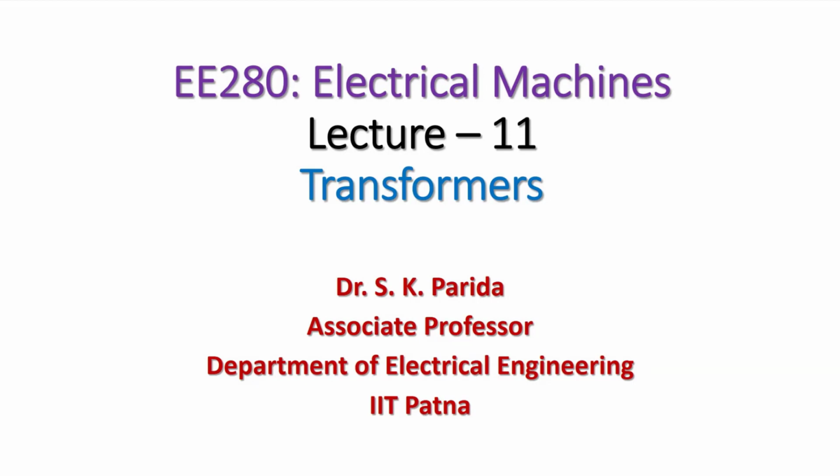And also I explained the importance of approximation, why we need the approximation so that the calculation will become easier. And this approximate equivalent circuit is also useful for determining the parameters of the transformer. In this lecture also we'll talk about how to determine the parameters like the resistances, reactances, the magnetizing reactance and the core loss resistance, how we can determine these parameters experimentally.